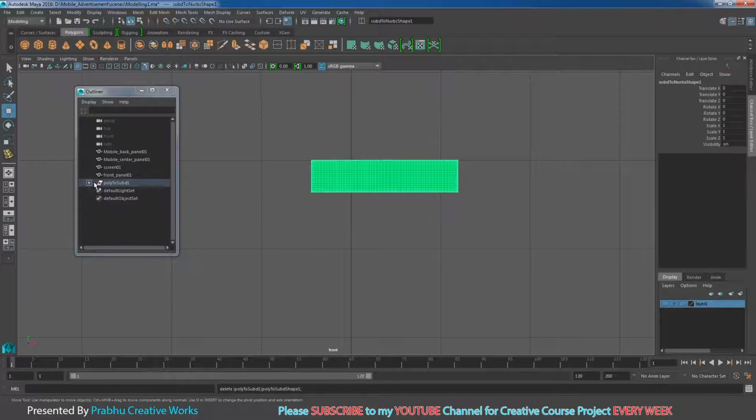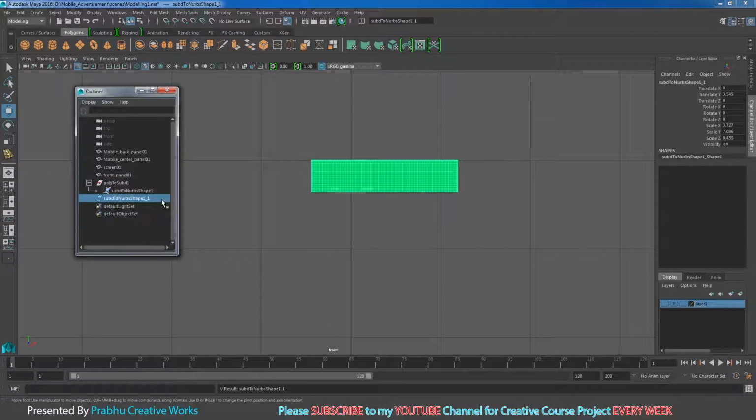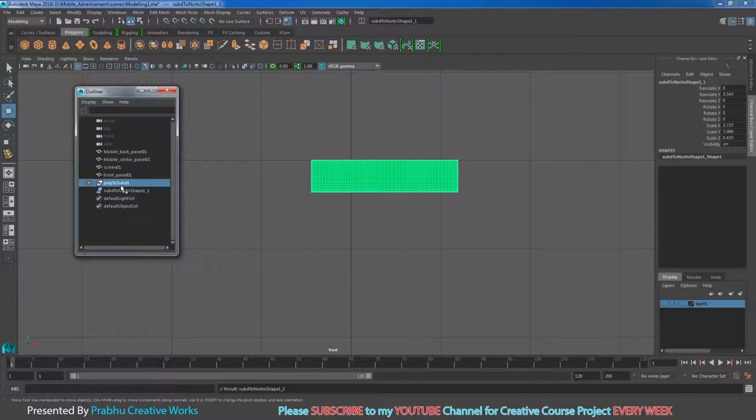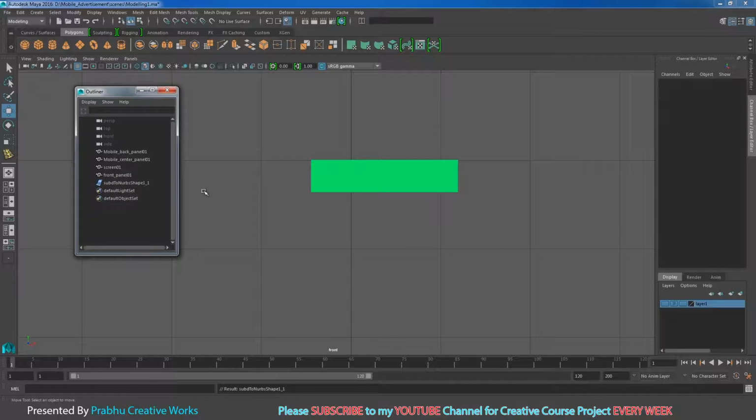So here we have some groups over here. So I will extend this one. I extend this group. So I will select my sub D to NURBS shape 1 and press Shift P to unparent. Now go to edit, delete by type and choose history. So now I select this group and press delete on the keyboard.